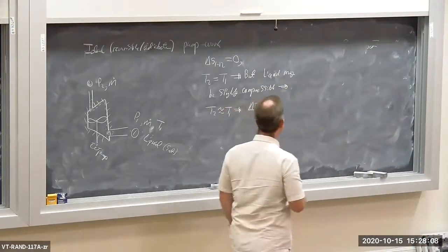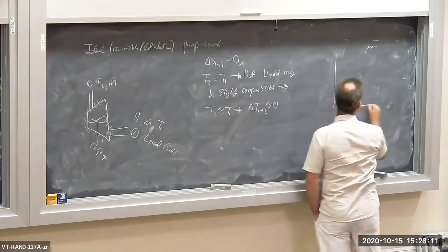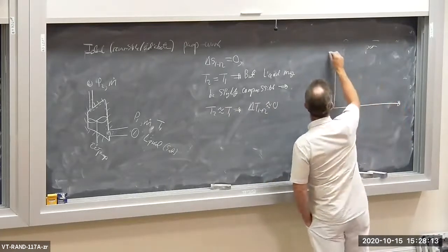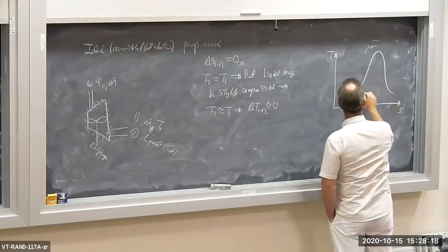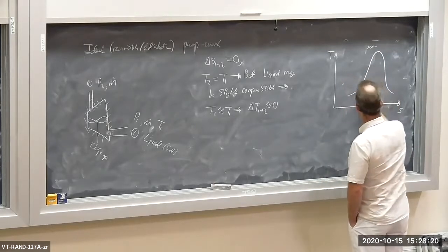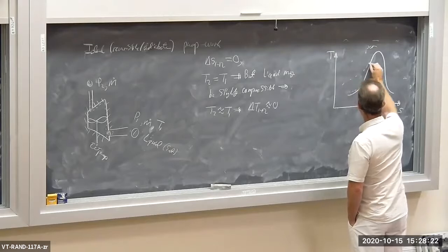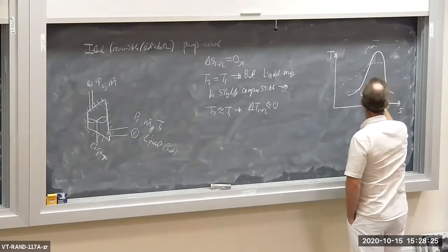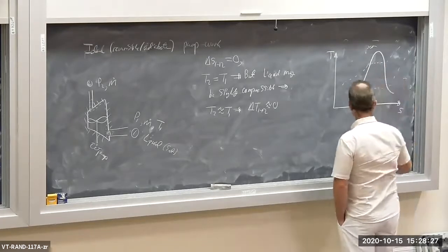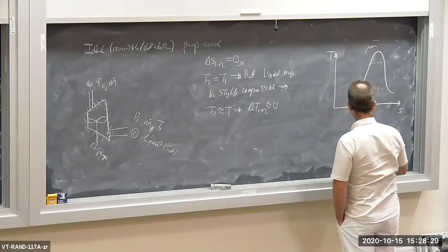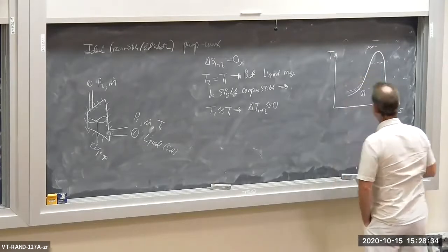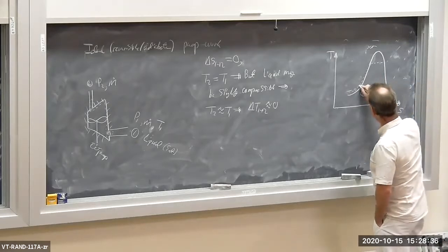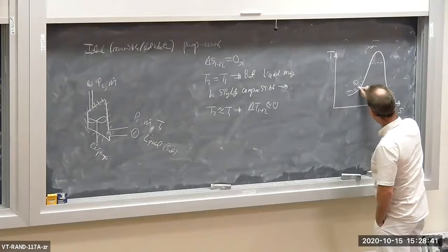So as far as the TS diagram is concerned, TS, here's our dome. Here's state 1, which is a saturated liquid. Here's the P min and a P max isobar. These isobars are a lot closer together. There we go. That looks better. So there's state 1. State 2 has a very, very small temperature change.